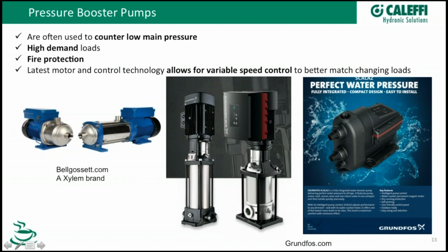You can see some vertical versions of it here. Some of these you can see have a kind of a brain on them, have the drive built into them, probably a variable frequency drive or some kind of electronic drive on that pump to vary the speed of it. These, of course, will all be stainless steel. Since they're moving potable water, we don't want to have any rust, which you would have with a cast iron body pump.